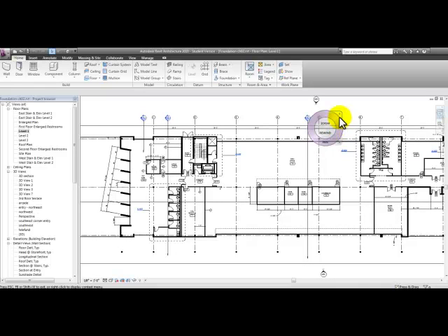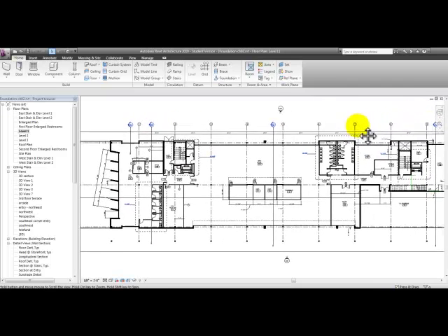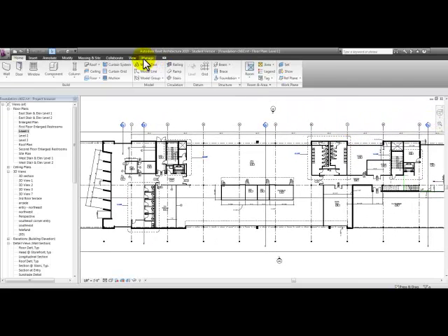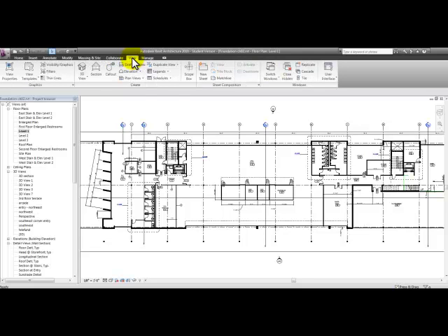I'm going to close out of the steering wheel here and show you how to turn on and off this navigation bar. One way is to go to the View tab here at the top and pick the User Interface icon and place a check mark in or out next to the navigation bar. It turns the navigation bar, that small bar here, off. I can go ahead and put the check mark back in to turn it on.